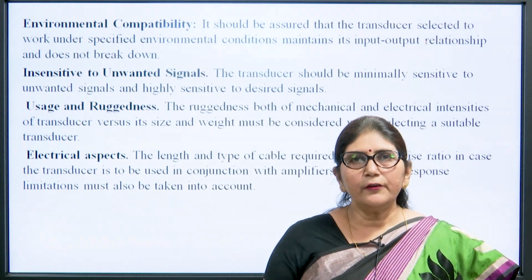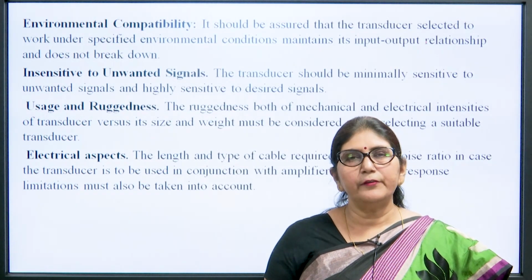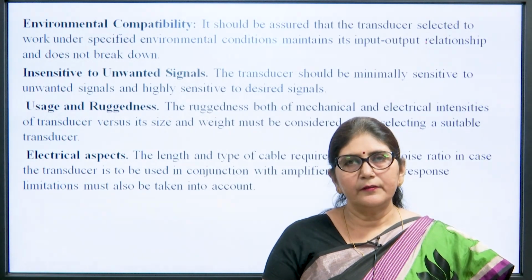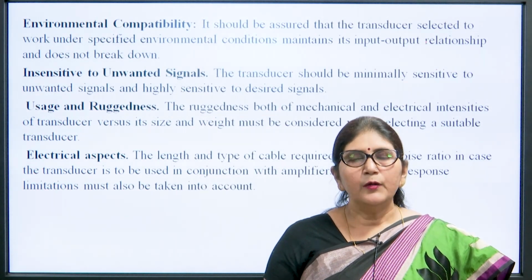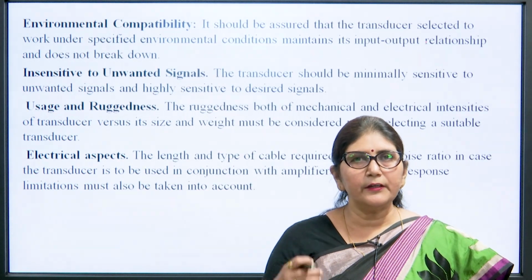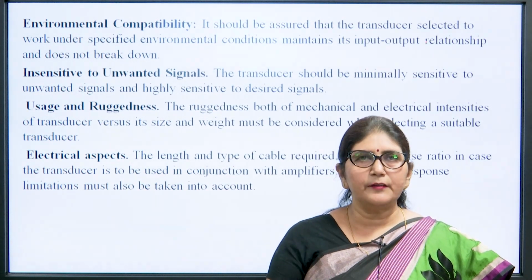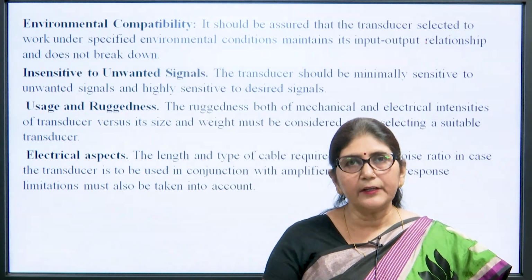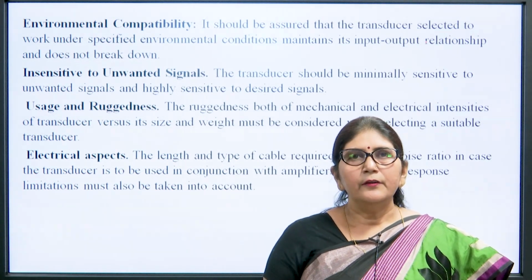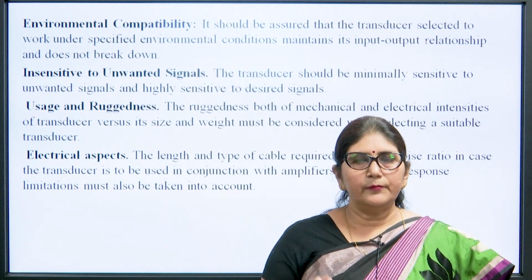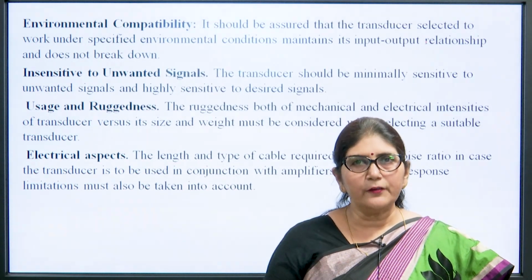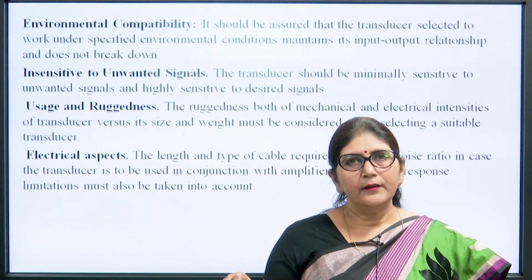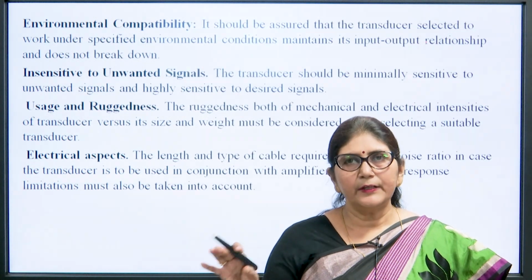So, the electrical length of cable required is also a very important part, in that it should not introduce noise while transmitting the signal, because the converted electrical signal has very little amplitude, and if noise is introduced, it is very difficult to remove that noise. And if the output is passed through an amplifier, the amplifier should be a low noise amplifier.